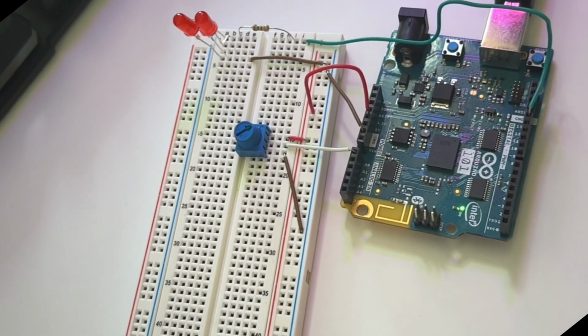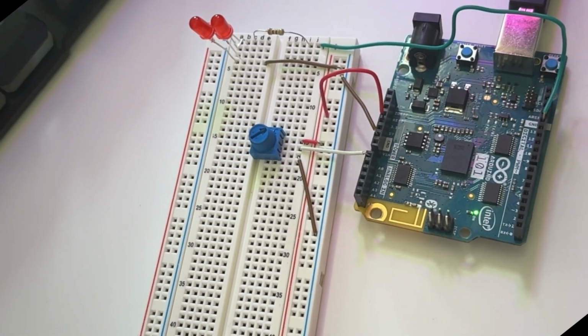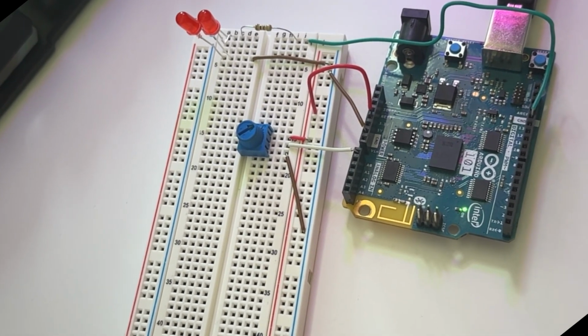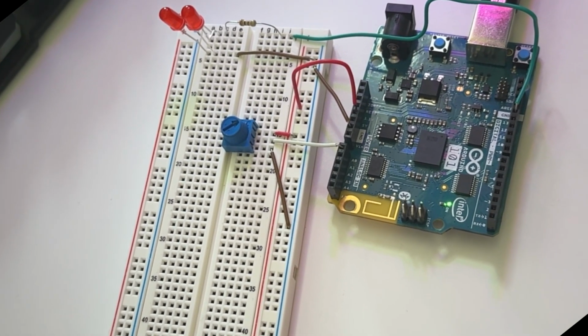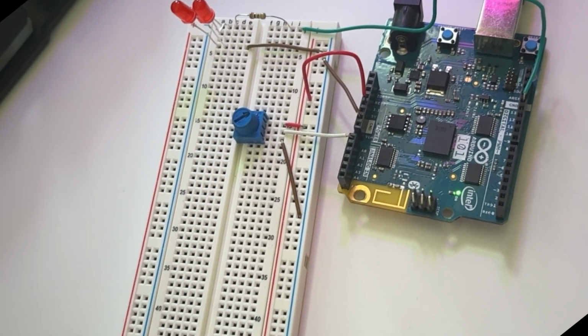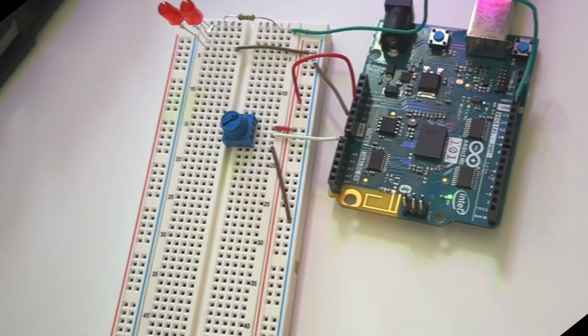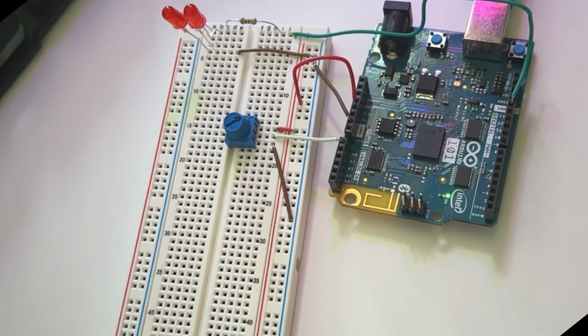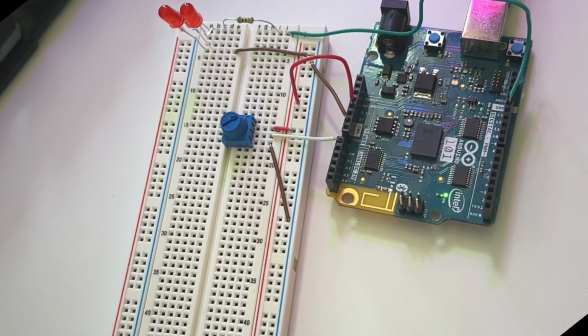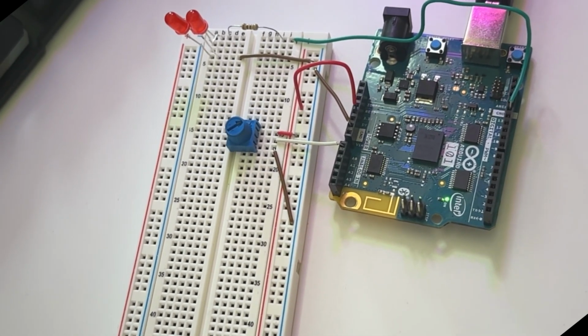This is the modified experiment number 3. What this now does is, depending on the 0 to 1020 value the potentiometer gives out, it will either make the LEDs blink in Morse code SOS or my name, CLAY. If the value is from 0 to 5, it will make the LEDs turn off as they are now. If the value is from 5 to 500, it will make them blink in SOS, as I said, or if it's from 500 to 1020, it will make the LEDs blink in my name.